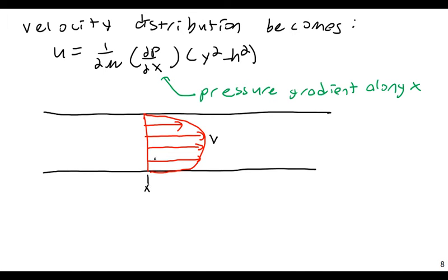So again, toward the walls of the pipe, at the top and the bottom of the pipe, or in this case the plate, you would have zero velocity. Then, as we've derived here, you'll have a parabolic relationship, and right at the center you'll have the peak velocity. So at a given cross section, all of the fluid in a pipe is not traveling at the same velocity.